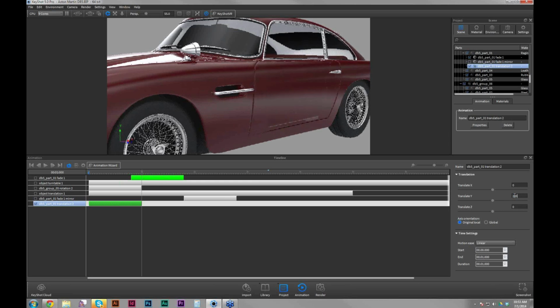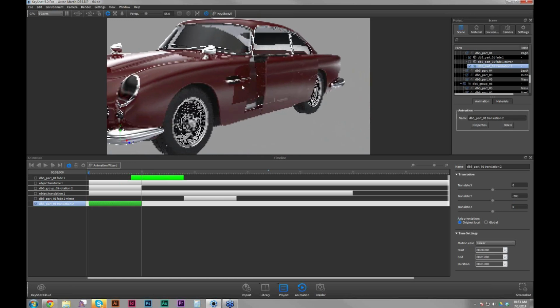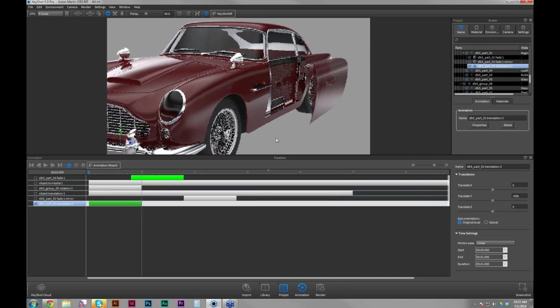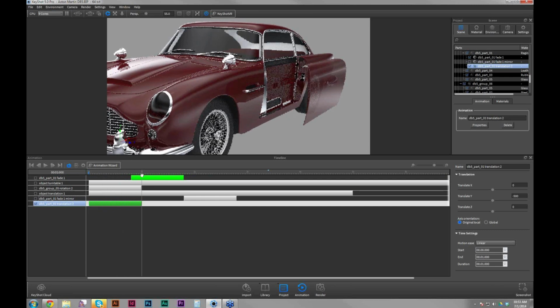That's probably negative y. Yeah, so if you have a part that you're moving through space for, let's say an exploded view, a really common application for animation is exploded views. So let's make it even further. So it's moving through space, like you have it moved out about 500 to kind of show the internal parts. You can scrub through it, you'll see it moving. And at the very end, you want it to collapse together.